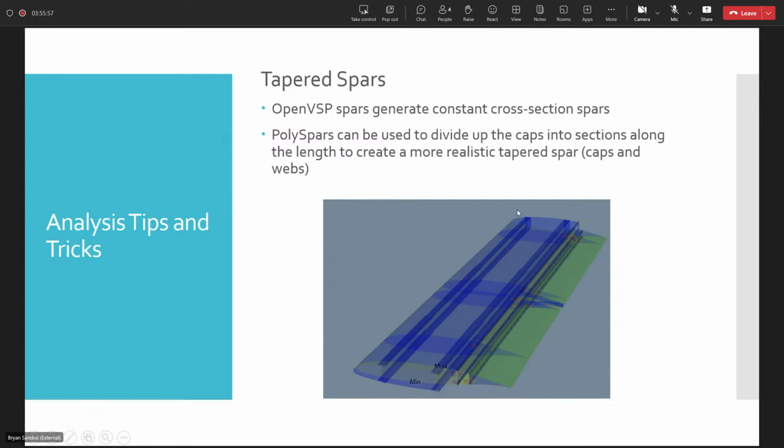It's important to note, if you're just doing a wing and you have a non-structural leading edge, you cut that off, and you're just looking at the wing box and you want to load that up, and you cut the trailing edge off, and then you apply your pressures, you're going to miss 30 or 40% of the load, because a lot of it's getting applied up here, and then some of it's getting applied back here. So if that's what you're trying to do, you probably need to take your loads and drive them down to discrete loads that you can apply at sections along the wing instead of this pressure mapping.